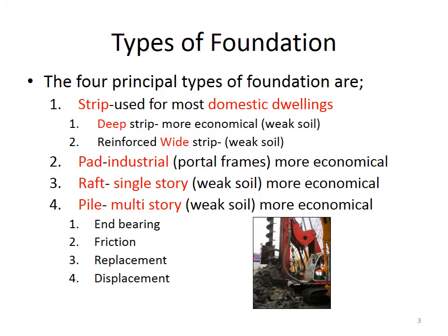The third type of pile foundation is called a replacement pile. This is where we basically drill a hole down into the ground and then it's filled with concrete. Sometimes reinforcing bars are placed into that hole as well before the concrete is poured.